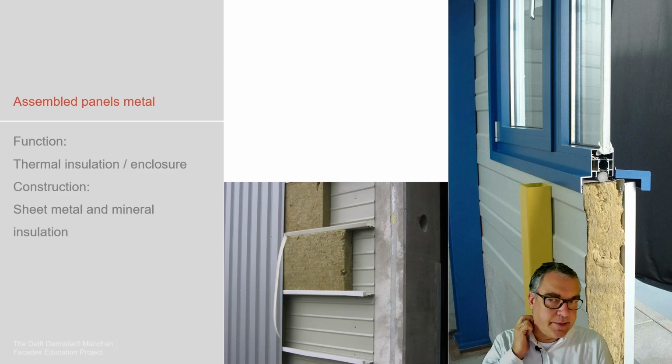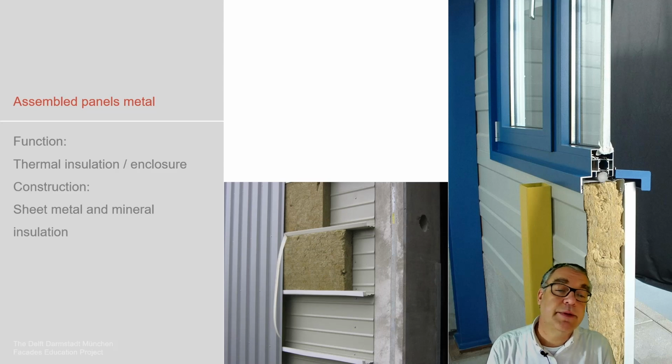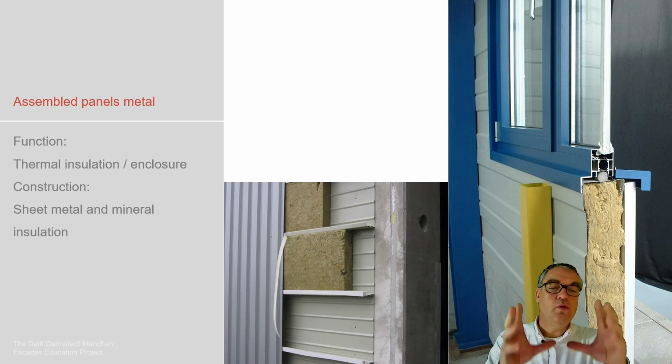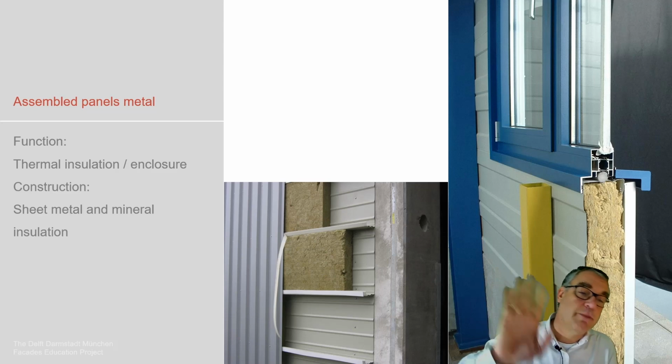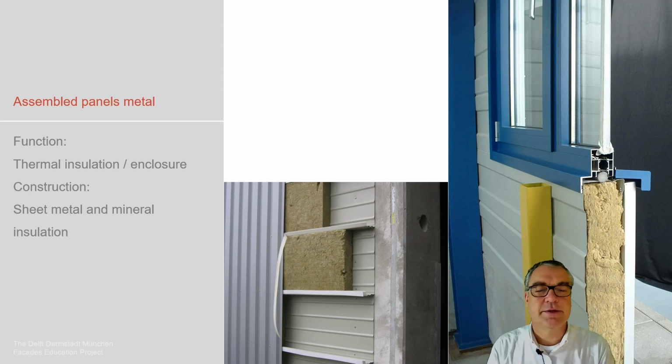The assembled sheet metal panel setup is shown here. There's an inner sheet metal, which is cold rolled in a way that the geometry allows an insulation to be added, and then there's an outer sheet metal which is installed on top of this to create this entire insulated unit as an assembled sandwich panel package. Again, this is very reasonable in terms of budget, so used for large structures, but does not perform that well in terms of acoustics, which brings us to the next